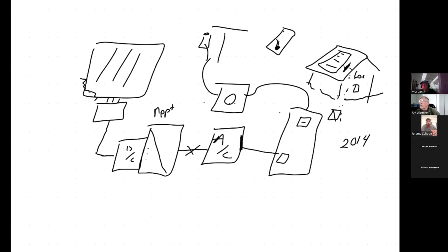So if I'm putting up 20 of them, I just spent $4,000 on these little microinverters, where I could buy a regular inverter for maybe $2,000. And the bigger the array, the more expensive it gets, and so on and so forth. So then a company called SolarEdge said, you know what we could do is instead of putting the whole inverter up there, we'll just get a little piece of electronic device and stick it up there that has rapid shutdown and the anti-islanding at the panel, and then have an inverter that it connects to.